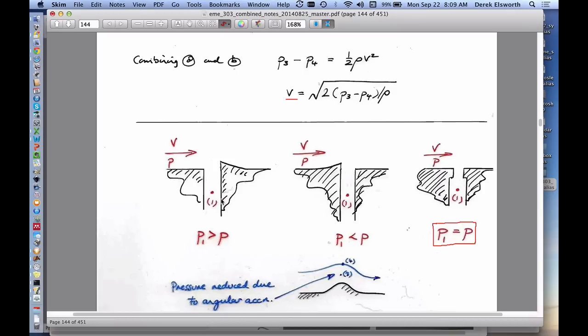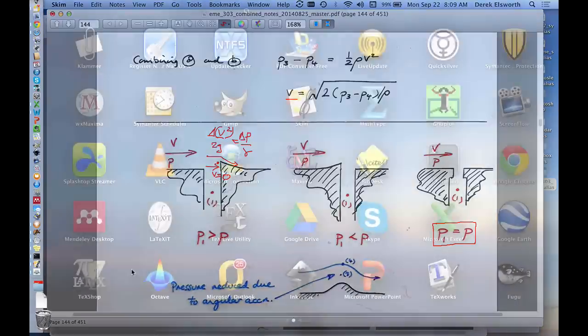If you happen to misdesign it so that you had a lip on it on the downstream side or the upstream side, then you can imagine from what we know about Bernoulli what would happen to that. If it's on the downstream side, you could imagine that a portion of the velocity here, instead of going nicely over the top, would be 0. And if it's 0, then you get a portion of pressure head contributed, which would be detracting from the, you get a pressure developed by killing this. So if you change velocity squared, I guess it has to be the bracketed term, you'd get a change in pressure that results from that. And so you get a spurious pressure which you don't want. So you probably don't want this.